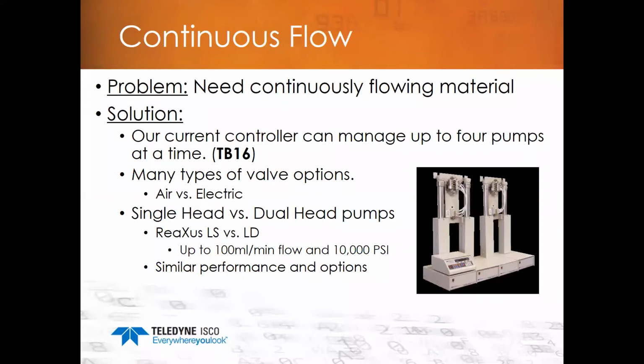Very simple. Does the customer need the flow to be a continuous and steady stream? Do they need a start and stop? And do they need pulseless or not pulseless? Because when you're looking at continuous flow, pulsation is definitely something that comes into play, and they need to consider that. And then how much of a continuous flow? Is it just going to be a pass-through? You're going to have a large vat of something and it's going to move the fluid over to another vat of something else? Or is it timed? How long do you need the pumps to be running?